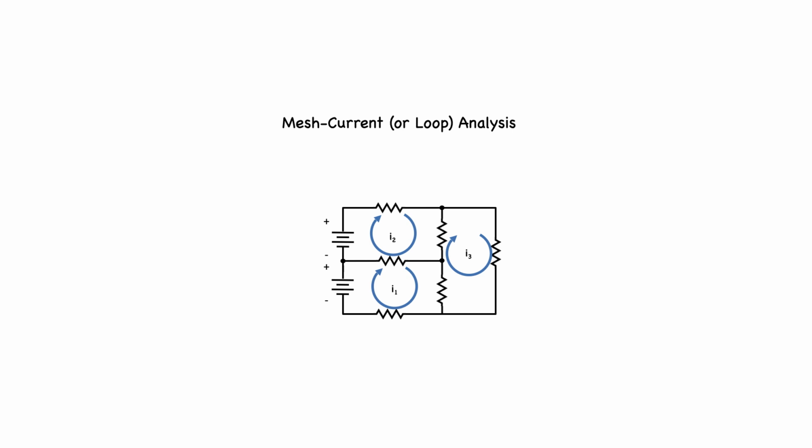The current flowing through the bottom resistor looks like this, and we're going to get a voltage drop across it as I've indicated, with a plus and minus. The resistor in the loop of the 3 meshes, because of the current I2 flowing in that direction, will set up a voltage drop from positive to negative as in the diagram. And in loop 3, the outermost resistor, because of the current I3, will have a voltage drop as indicated, plus to minus.